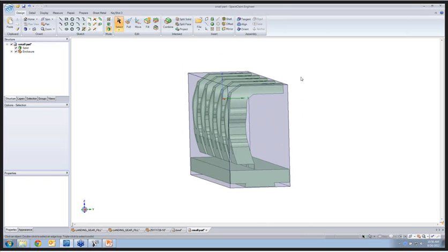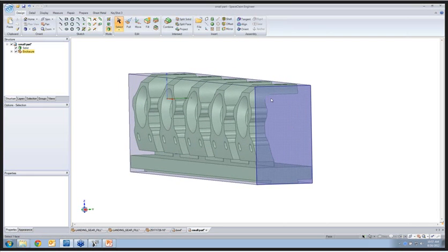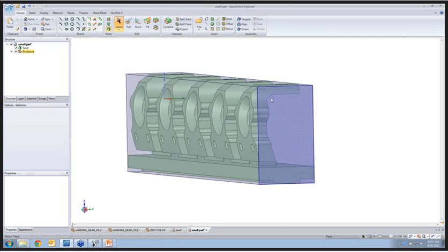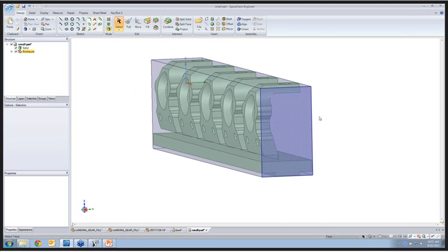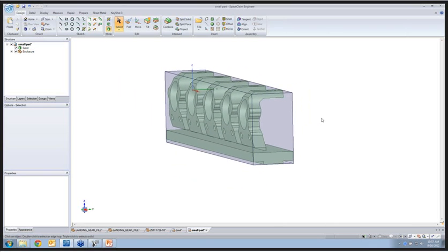So this is great because you eliminate air cutting. You know exactly where your tool needs to go, how fast it needs to go to get right up to this part, and then when it needs to slow down to start cutting. So you're drastically eliminating waste. You can use things like crash detection. In MasterCam, you can take advantage of all those types of things because you can export solids, any kind of solid, from SpaceClaim into MasterCam now. Okay, so that's a good example to show how you can fixture something up and create solids that represent the block that you start from.